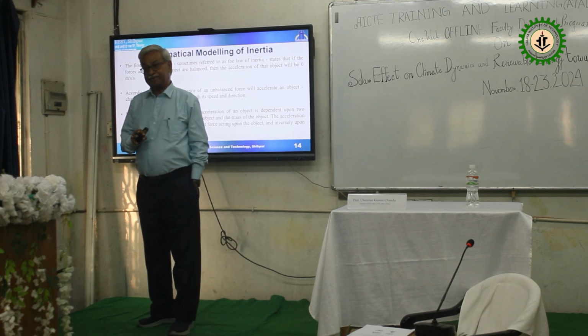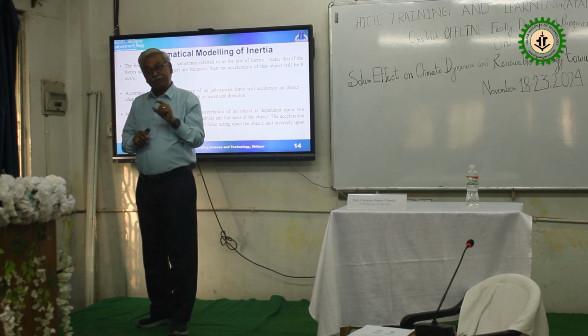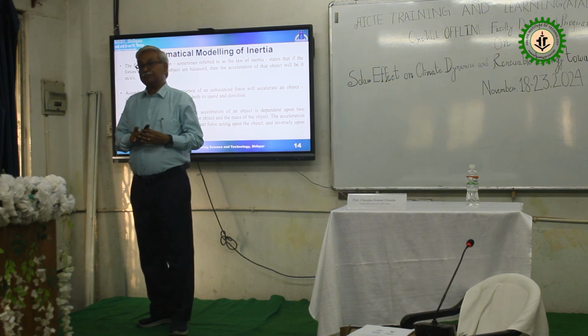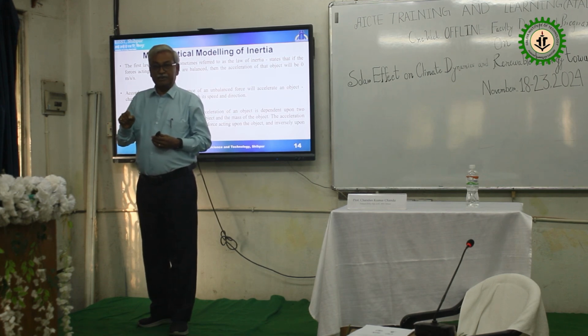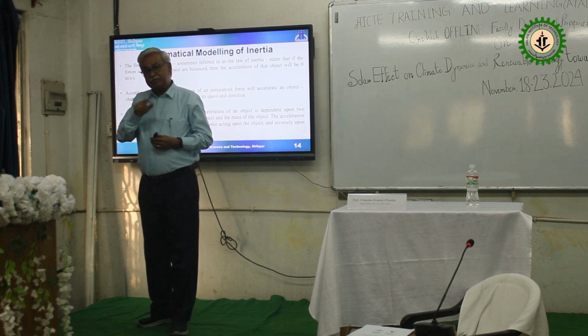But here in the synchronous generator, another important aspect is there. When you talk about the stability of a grid, especially active power stability, then we write that P transmission is equal to EV upon X sine delta. If you note the power flow expression, delta is the power angle, EV by X sine delta. So it is basically a sinusoidal function, a nonlinear function.